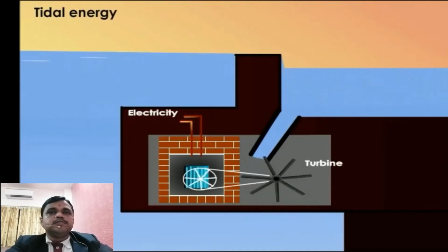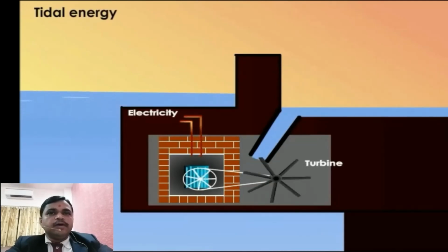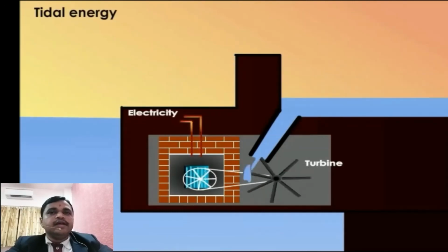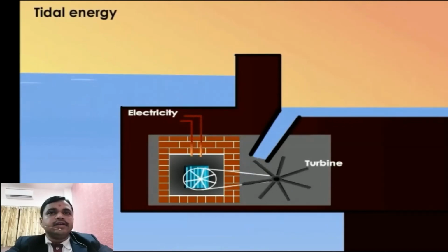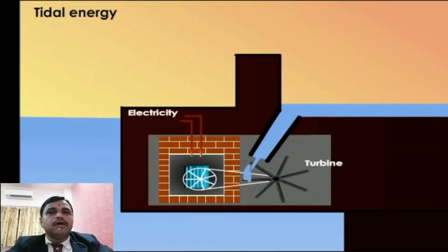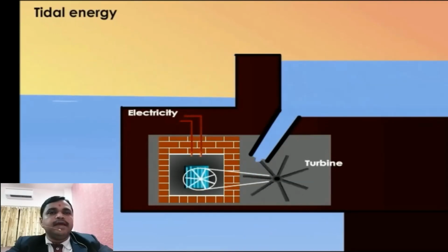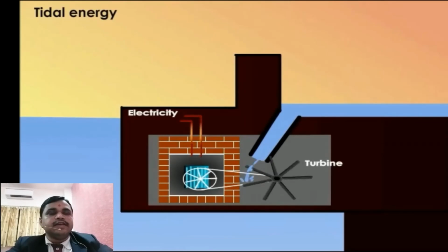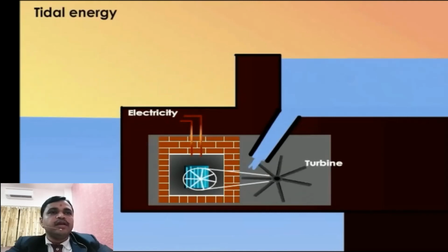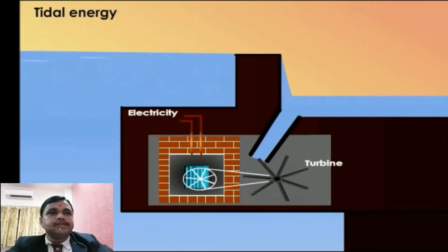The main parts or components of tidal energy are the powerhouse, dam and basin, and sluiceway. The turbine, electric generators and other auxiliary equipment are the main equipment of the powerhouse. The function of the dam is to form a barrier between the sea and basin. The sluiceways are used either to fill up or empty the basin during the low tide as per operational requirement.